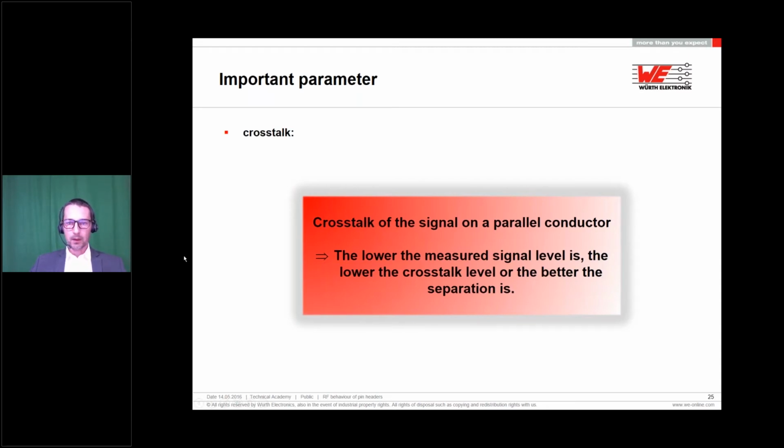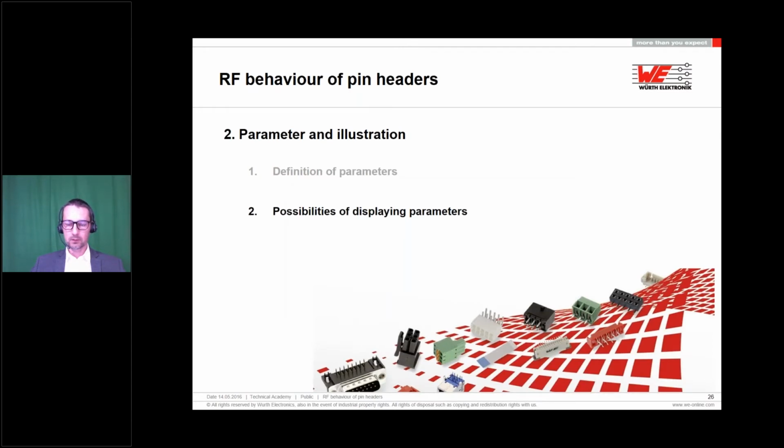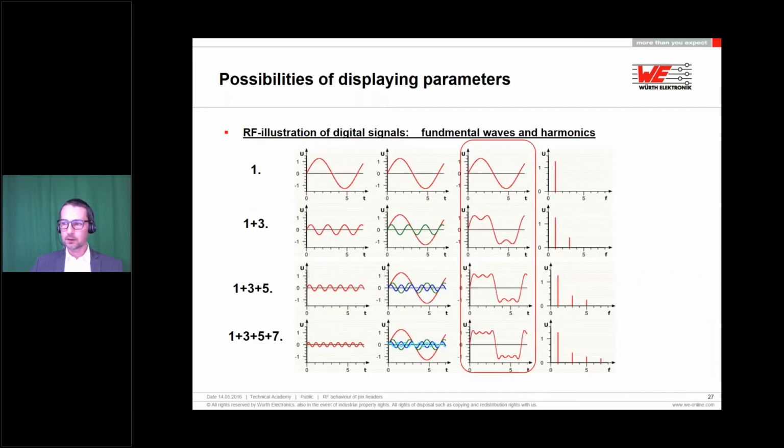So how can we now look at these parameters that we measure? What can we do with them? How does this signal come about? If we start from scratch and go back to our example for USB, or any digital signal more or less, if we transmit a signal on this transmission line, we typically have square shaped signals for digital signals.